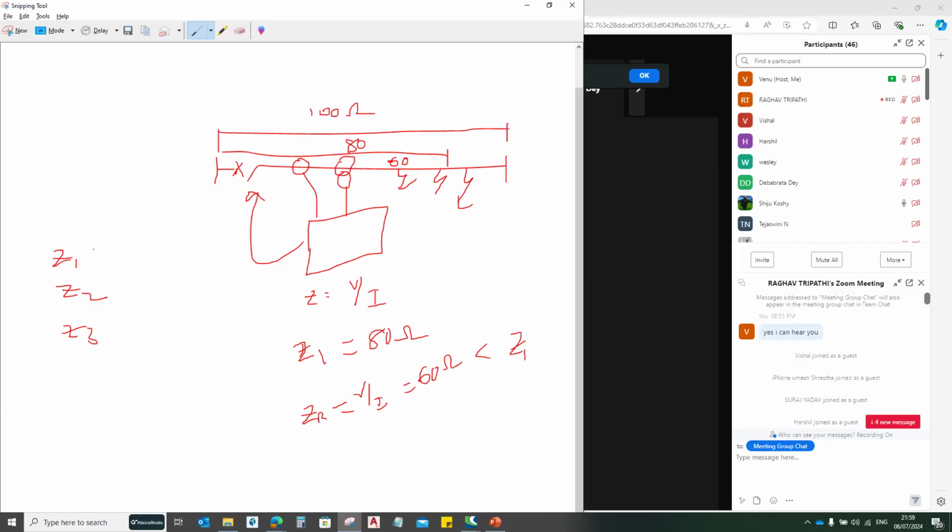I will take that as the basic value, and based on that I am going to set Z1 at 80% of the protected line, that is 80% of ZL. Then Z2 will be 120% of my protected ZL, or up to 150% of ZL. Then Z3 will be 150% of my protected line plus 120% of the next shortest feeder from the other end substation.